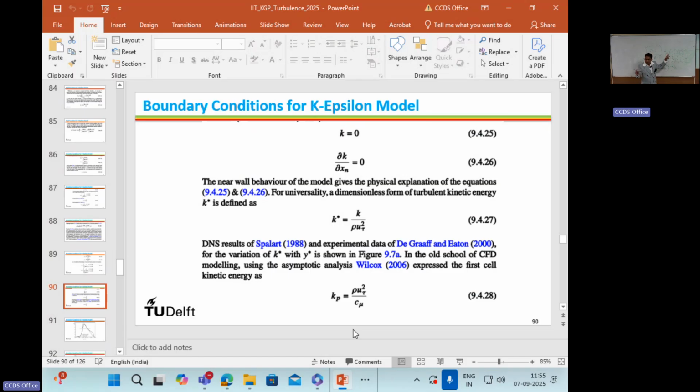If it is a high Reynolds number model, where you are using any wall function, the governing equations are not solved in the wall adjacent cell. They solve everywhere inside the domain except the wall adjacent cell. But if it is a low Reynolds number model, we will decide what that is subsequently, then the governing equations are solved throughout the domain, in all cells.